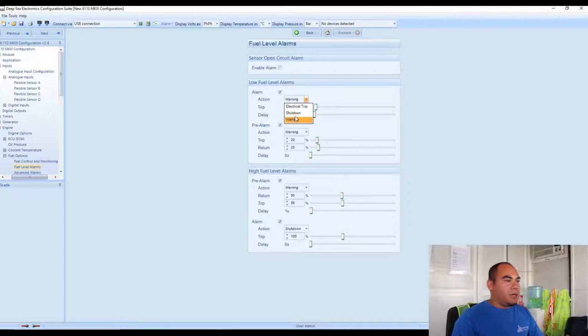But if you don't have the pump, just make it shut down, so it doesn't make trouble when you start, because sometimes if you did not make shutdown, this warning will let it finish all your fuel in the tank, so the air catches and it is very difficult for you to start back your engine. You need to bleed, or troubleshoot why it's not starting.